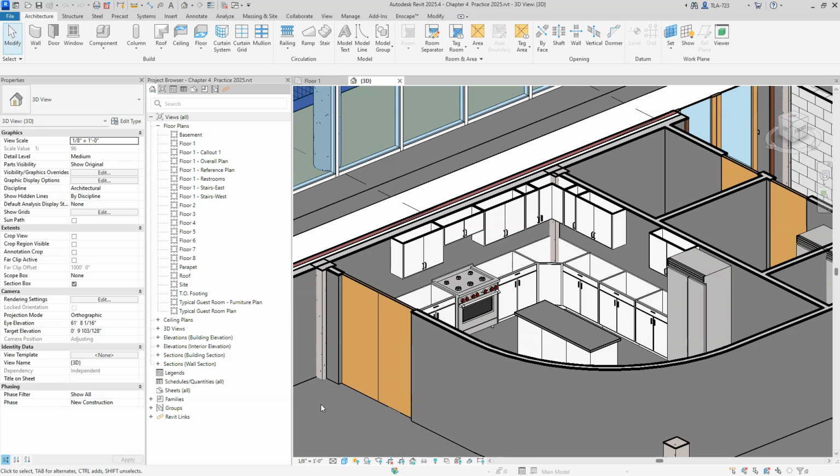However, that corner to corner distance does have to include the gypsum board because cabinets are fastened to a finished wall, not to a framed wall. So we have to factor in that 1/2-inch thickness of gypsum board. And in speaking with contractors who actually do install cabinets for a living, I've been told on a few different occasions that it's a good idea to add a 1 or 2 inch buffer. So whatever that wall-to-wall calculation is, add 1 or 2 inches on there because typically the framers and the drywall finishers are not going to end up with a very, very precise distance. So we don't want to have to cut the cabinets to make them fit.